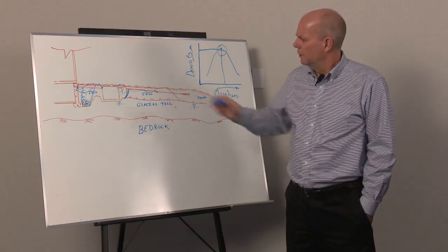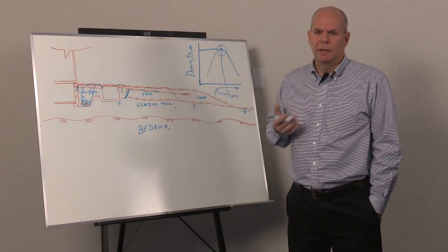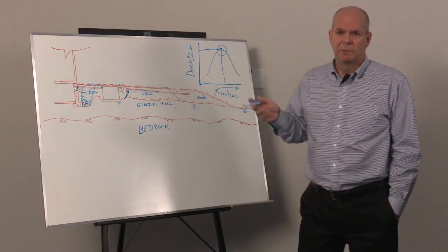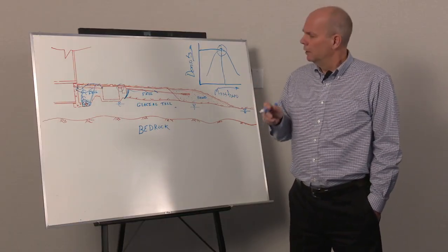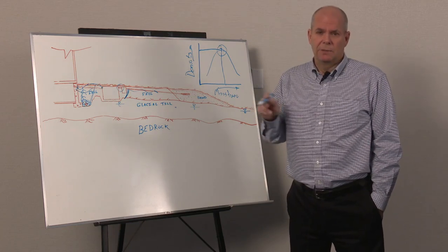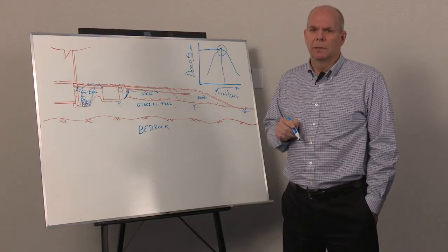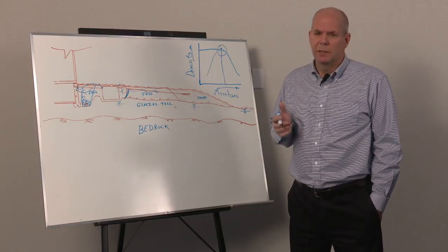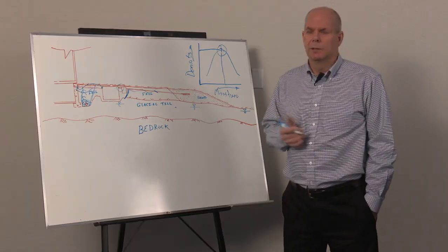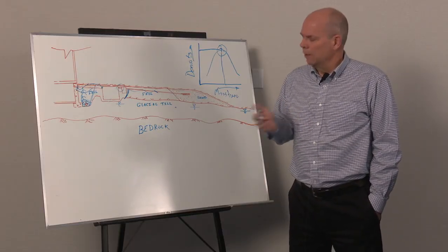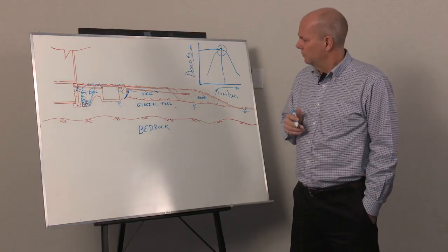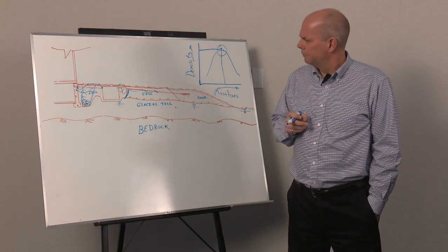Bedding systems for your pipes, if you're putting in bedding sand or bedding gravel, has to be compatible with the material under it. Sometimes you may be on a site that's backfilled with rock fill, boulder fill, or whatever. You can't put in a sand backfill on top of that material and risk losing all your sand fines down in among the voids of the boulders or the gravel or whatever happens to be there. So geotextile separating materials is often the way to deal with that. Usually if you've got fine-grained soils derived from the tills and you're putting sands on top of them, there should be no issue with filtration of one material into the other.